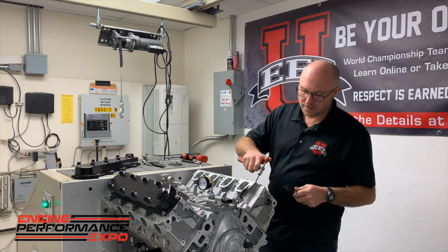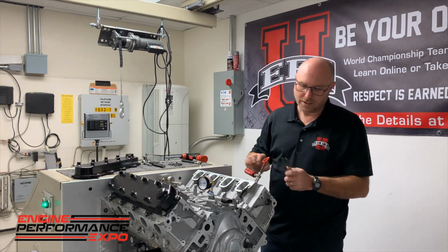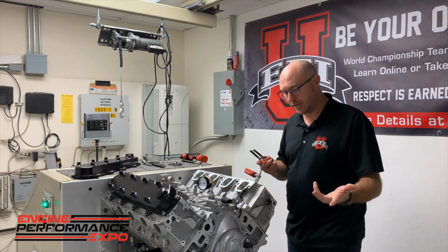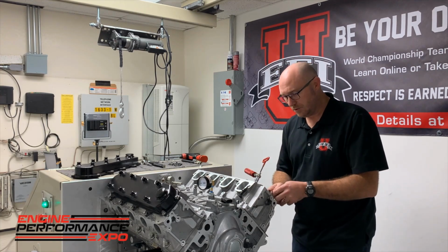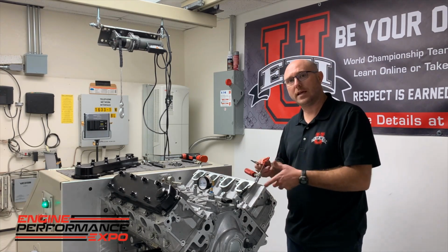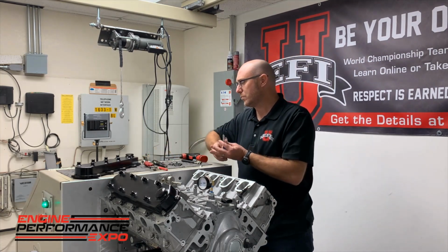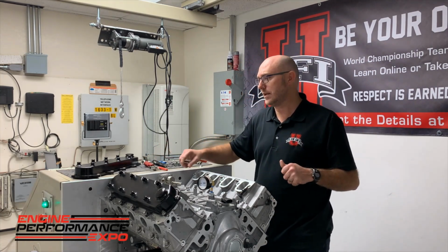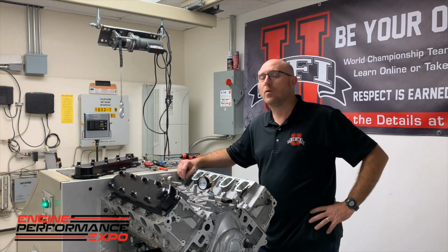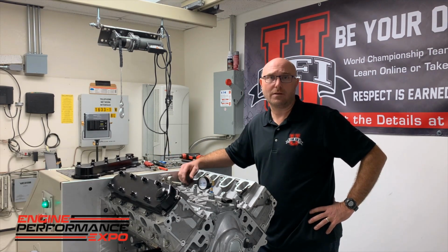So we just come over here, we grab our wrench on the crankshaft, and we roll it around to where I'm ready to check my lash. Take my lash tool. Okay, that's good. Move to the next one. We'll do that often just to make sure that we don't have any issues with reliability or stability in the valve train, especially on engines where we don't have the ability to use the laser for dynamic tracking.